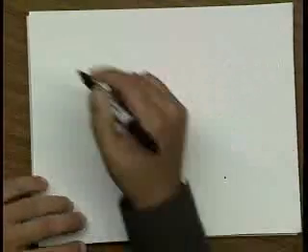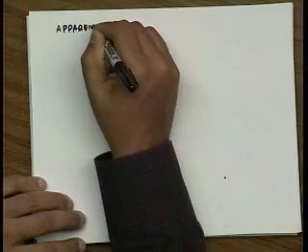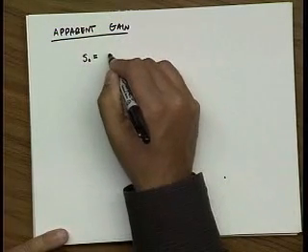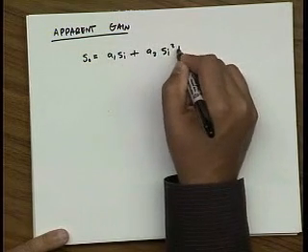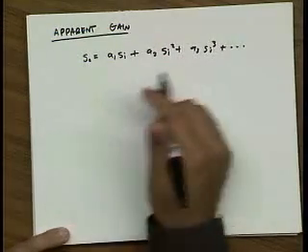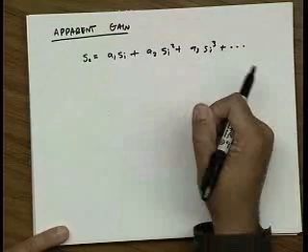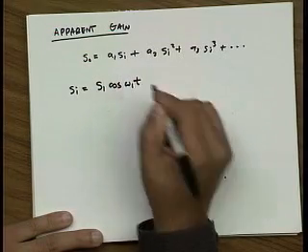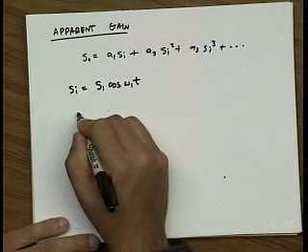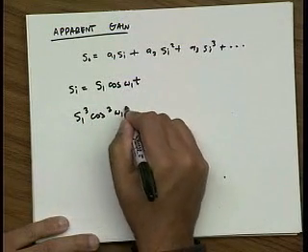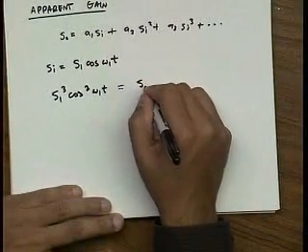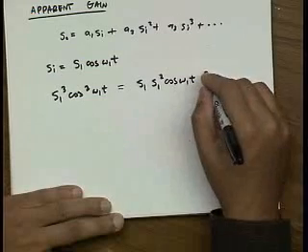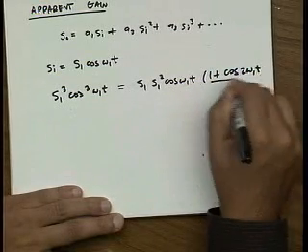All right, so let's calculate the apparent gain based on the small signal analysis that we did. Remember, we assume that we can do a Taylor series expansion on the nonlinearity, and let's say that the cubic term is sufficient to understand the behavior of the system. If we put in an input S1 cosine omega 1t, and look at the cubic term, S1 cubed cosine cubed omega 1t, I can never remember these, so I just do it from scratch. I can write this as S1 squared cosine omega 1t times cosine squared, which I do remember: 1 plus cosine 2 omega 1t divided by 2.